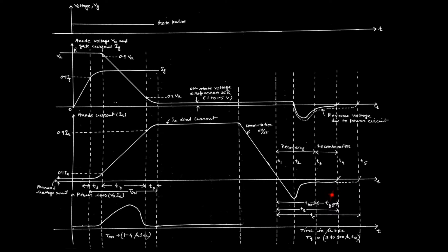The total time taken during this is defined as, suppose, TC. This TC is always greater than TQ, otherwise we cannot say a reliable turn-off process has been done. Suppose the switch has been turned off during TQ and we again try to switch on the device, then the breakover voltage can differ.